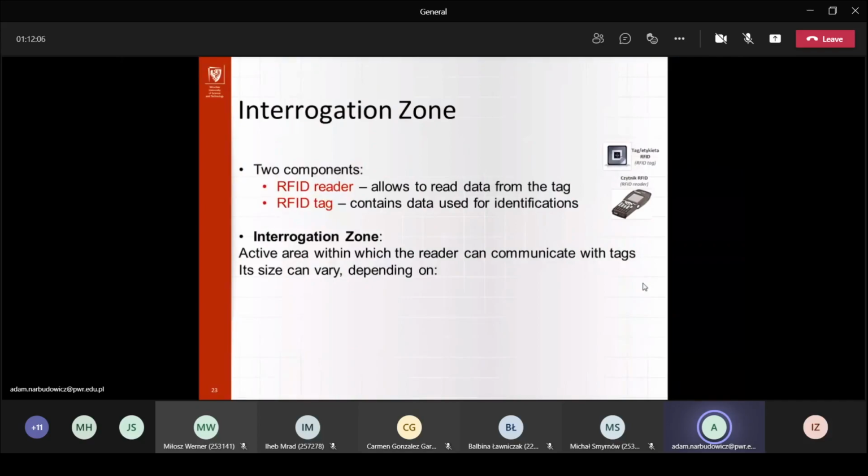But all of the accepted power will be used to power the second link, which again is the case with power 2 of the distance. Because those two links are in series, overall the power of the system will deteriorate with power 4, simply because you first need to deliver the energy wirelessly and then transmit it back. That's the very strict limitation on why RFID systems typically have a low interrogation zone range of up to a few meters.